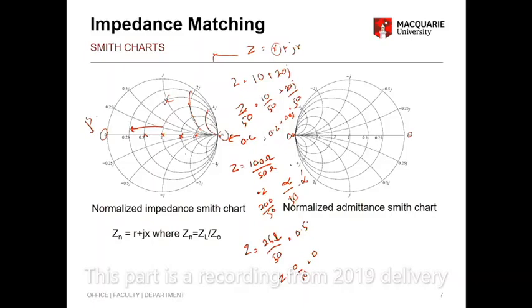Now, you'll see these circles, they represent reactance, all these circles. So you have 0.25j, 0.5j, j, 2j, 4j. In between them there will be lines, it's just that they're not drawn. So in here there will be 0.375j. So you can actually dissect it and have multiple of those lines.